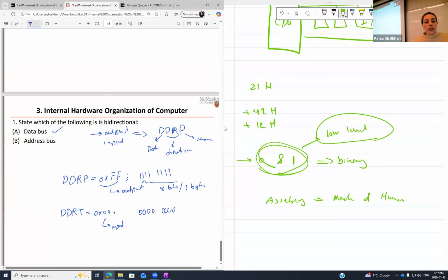This part of it is the port name. It could change and it could become a different port. But the DDR is always DDR. Data direction means I'm assigning some of the ports to become either input or output. Can I bitwise a direction? Can I adjust the same port to become both input and output?